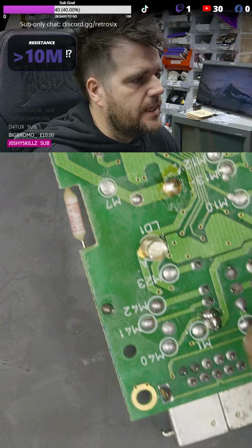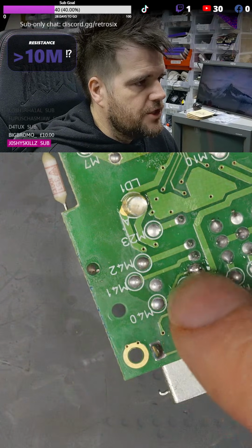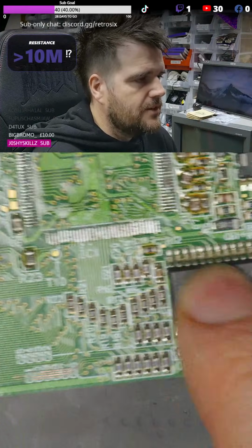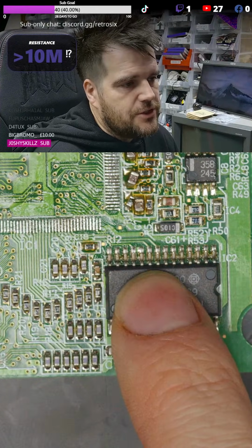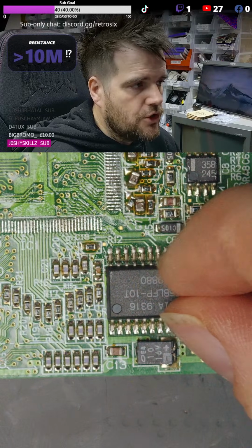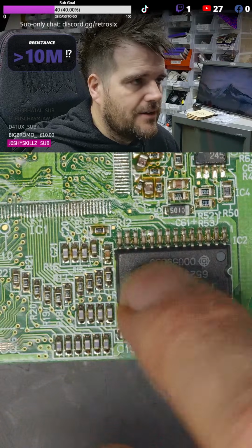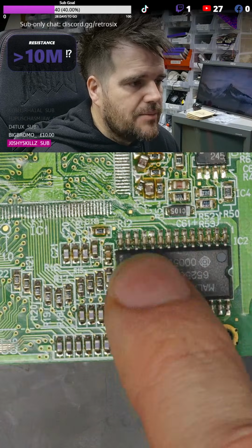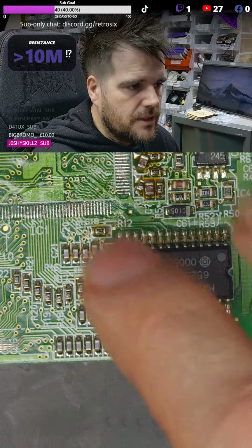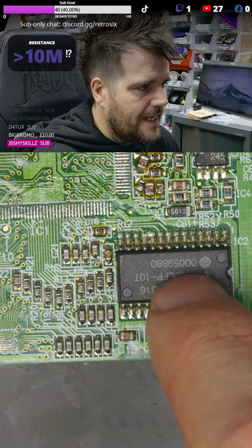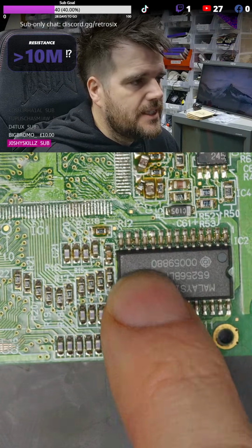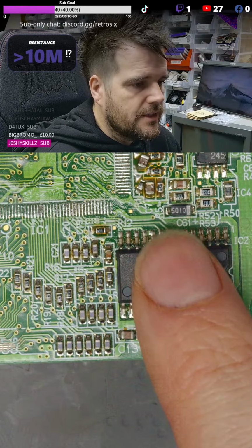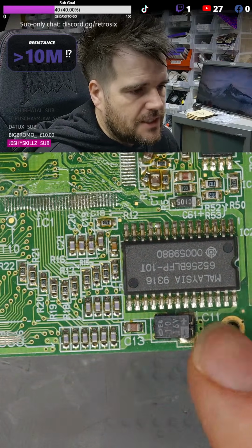You've got a dead short, which is literally a bridge. You've got a low ohm short, which is typically component failure, or say this IC fails internally, this IC might just heat up because inside it's pulling too much current to handle and it dissipates the heat. So again, thermal would pick that up easy. None of the others would really point you to this location. IPA in this case would probably work. This would bubble because it'd get hot and the die in the center is what's getting hot. So you detect this with IPA. But 99% of the problems are always thermal is your best way of going to detect a short.